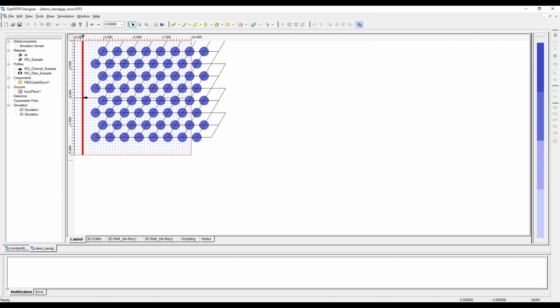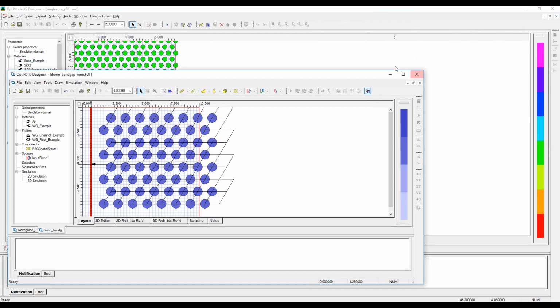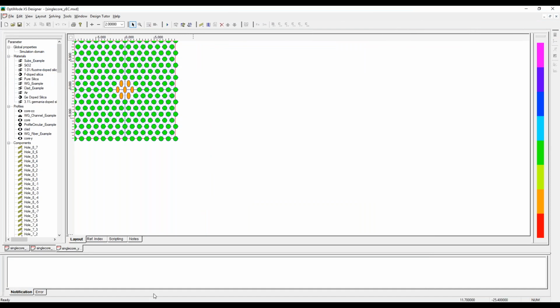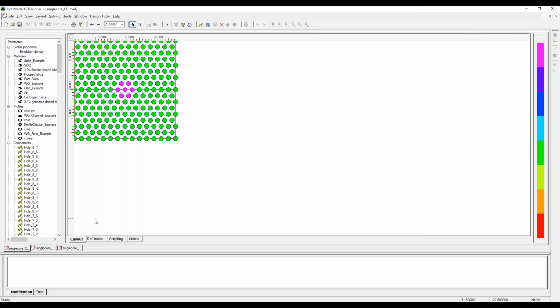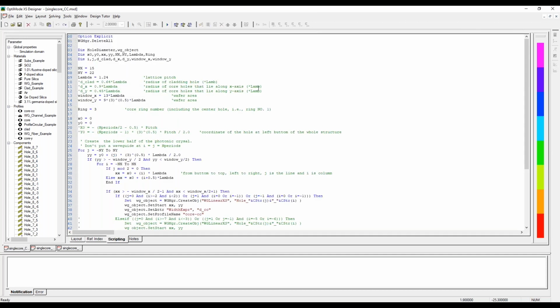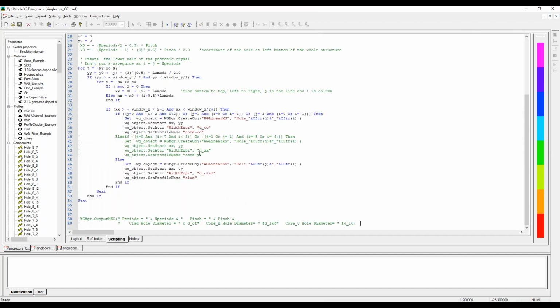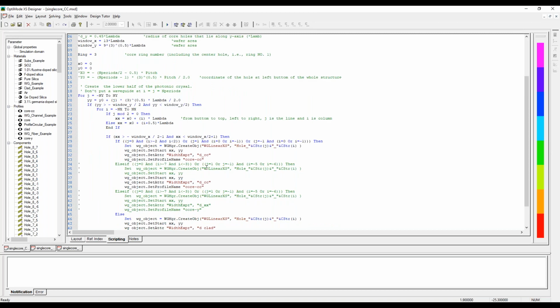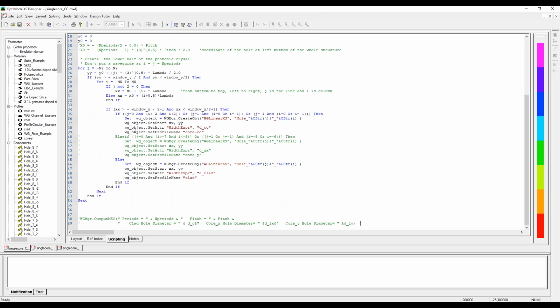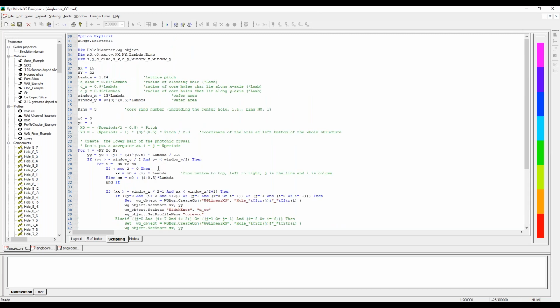So let's go back to the, not FDTD, but the mode solutions. So first I calculated these 3 modes, and the way I made the geometry is by using scripting, right? So I wrote these long scripts, which place all these elements, and we can have these available for you guys if you want to try it out yourself. They're not super complicated, although starting a new scripting language always takes some time. But essentially, I'm just looping through a loop, and it's creating these different objects depending on where it is geometrically and giving it materials.